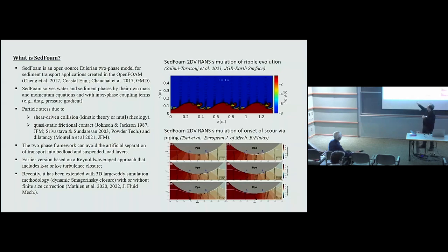Okay, but when that particle pressure is very large, it's going to kick into this Sanderson formulation, which is essentially a Coulomb type of formulation that links the particle pressure with the shear stress through a friction angle. And so that's how you can also deliver the shear further into the bed if it's sufficient. But once you have shear, then you trigger suspension. So there's an iterative process going on there at the bed.